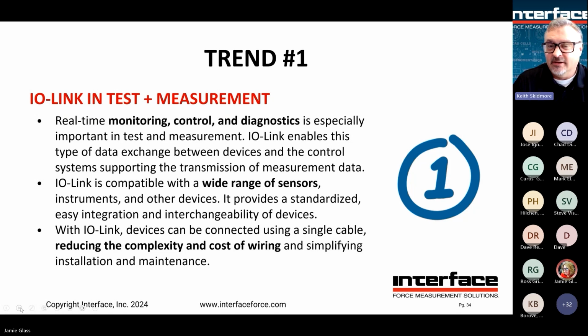In IO-Link, cabling is industry standard M12 cabling, so very cost effective. Again, it's 24-volt differential, so it's very noise immune, so you don't need twisted pairs, heavy shielding, any of that kind of stuff. It'll work pretty well on most any cabling.